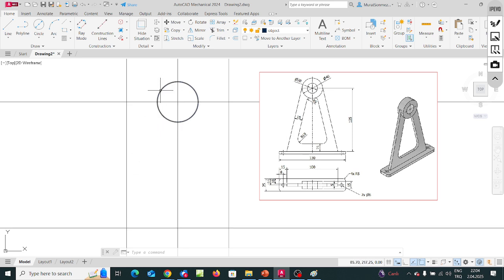It is tangent to the circle over there, and it ends at this intersection point. Select the single line creation option. Click on this. To be able to create a line as tangent to a circle or circle arc, there is a trick.